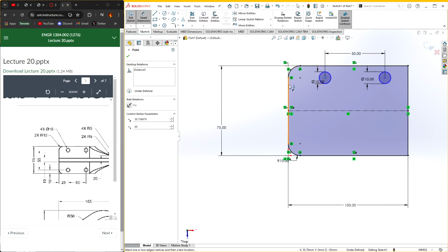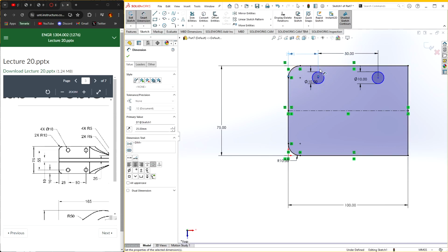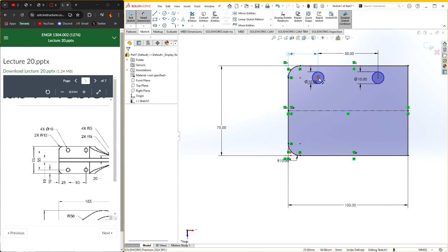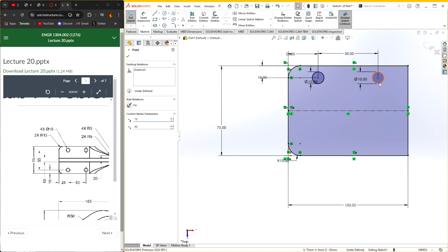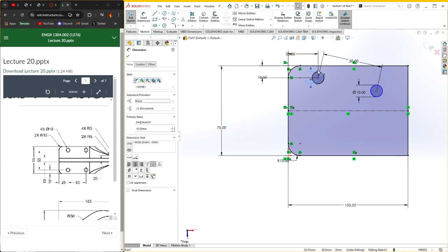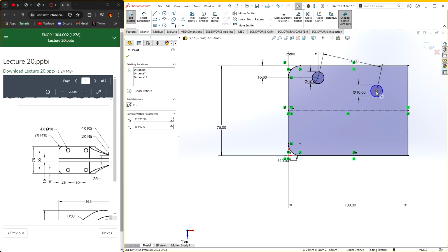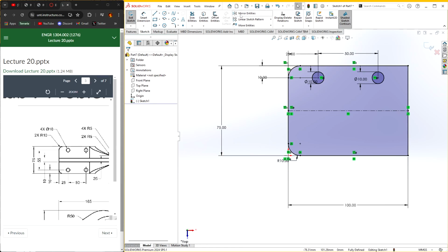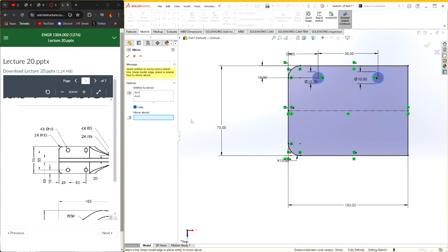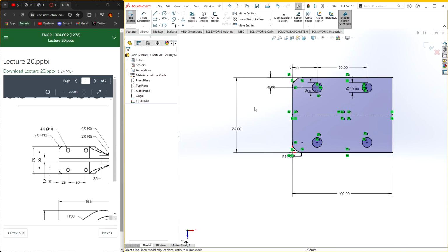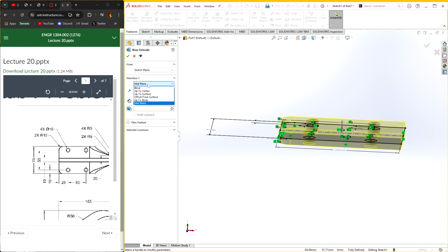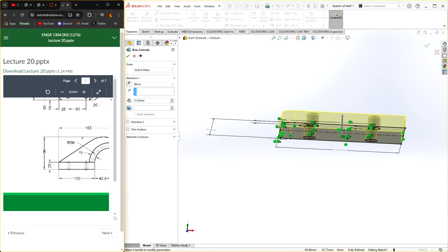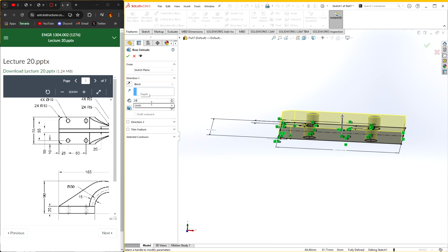The space between this point and this line should be 25. And the distance between this point and this line should be 10. And then this one, I'm just gonna set this to be horizontal with this one. And then I'm just gonna mirror both of these across this center line that we did. And then we're gonna extrude. It doesn't really matter how I extrude this, just as long as it gets extruded. This needs to be 20 millimeters tall. There we go.